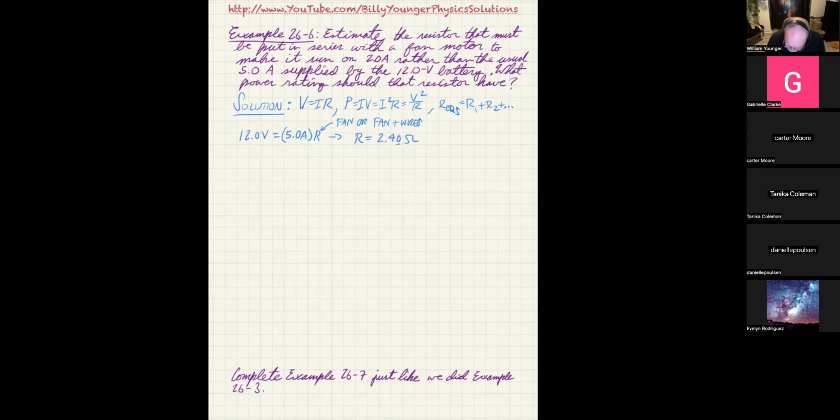All right. So now I've got that resistance. Now, what's going to happen is basically we're going to have this 12-volt battery, and it's running into a motor that has a resistance of 2.40 ohms. And then now what we're going to try to do is slip another resistor in here, R equals question mark. But now what we want is the current to just be 2.0 amps. So now what we're going to do is solve for little r, but we're going to use Ohm's law.